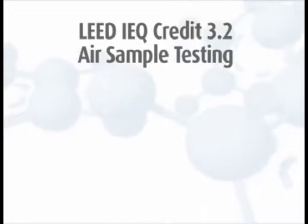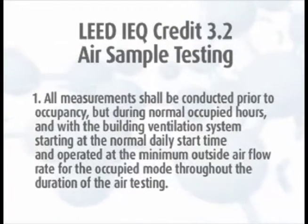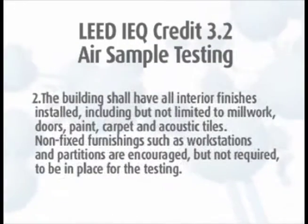LEED IEQ Credit 3.2 air sample testing should be conducted as follows. 1. All measurements shall be conducted prior to occupancy, but during normal occupied hours, and with the building ventilation system starting at the normal daily start time and operated at the minimum outside air flow rate for the occupied mode throughout the duration of the air testing. 2. The building shall have all interior finishes installed, including but not limited to millwork, doors, paint, carpet, and acoustic tiles. Non-fixed furnishings such as workstations and partitions are encouraged but not required to be in place for the testing.